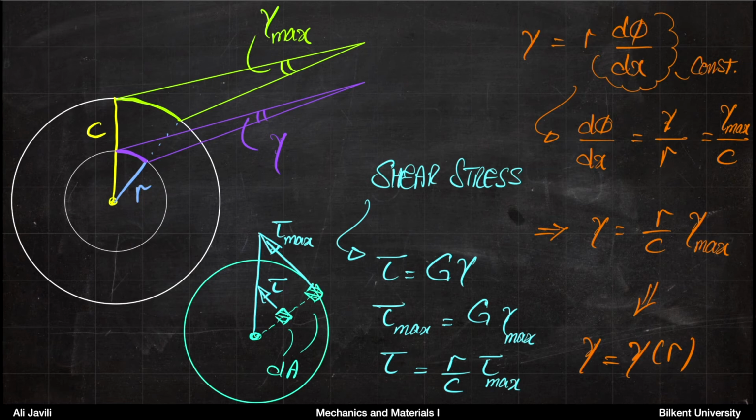And also you remember this is shear stress. So basically shear stress always works on an incremental area, let's say dA. And then if you want to think of the force corresponding to that shear stress, you should always think that dF is shear stress times dA. That would be a shear force.